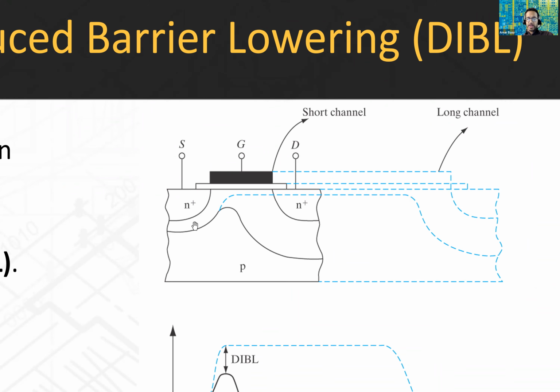This is an N-type semiconductor, and your substrate's P-type. So of course, between the N and P-type semiconductor, you have a depletion region. And we learned in module 5 how to calculate the width of that depletion region. So that is what is shown here. These two lines show you the size of the depletion region.